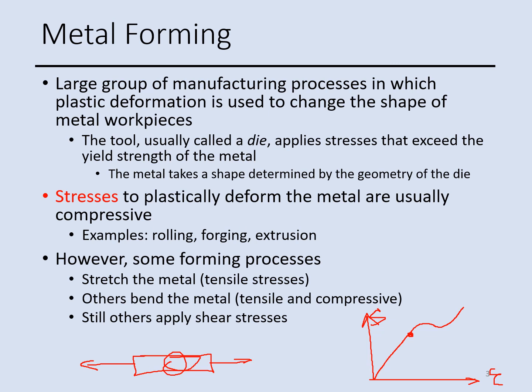So up to this point, in the linear plot, if you remove the stress, if you remove the load, the workpiece comes back to its original position, because up to here we have elastic deformation. It's called elastic. But after that threshold, which is called the yield strength, we go to plastic deformation. It means the material doesn't come back to its original shape.